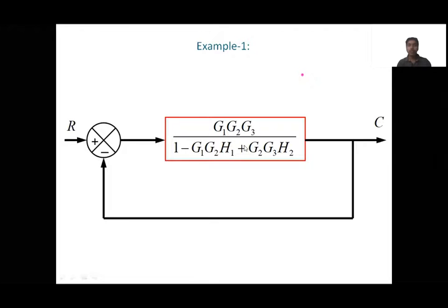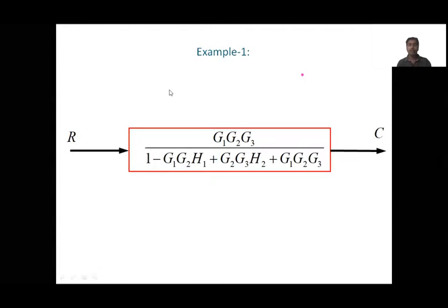Now see, this is again a single feedback loop, but here the feedback gain is 1, a unity feedback system. So again, say this is overall G and H is equal to 1, by the formula G by 1 plus GH, we substitute and simplify, and you will get like this. Now the overall system, the complicated big block diagram, is reduced to a single block like this.